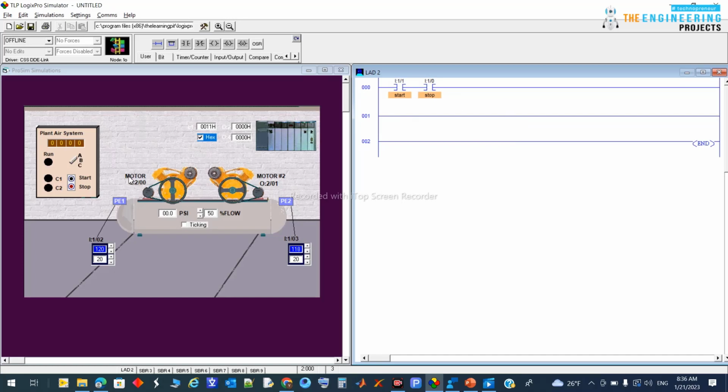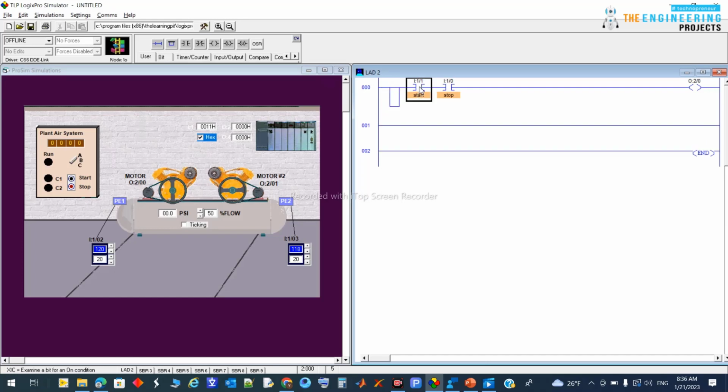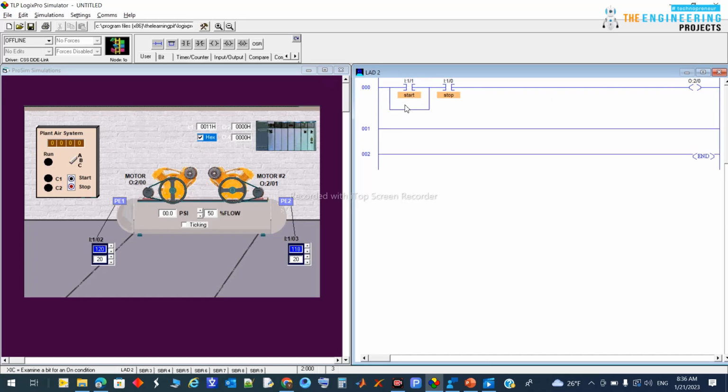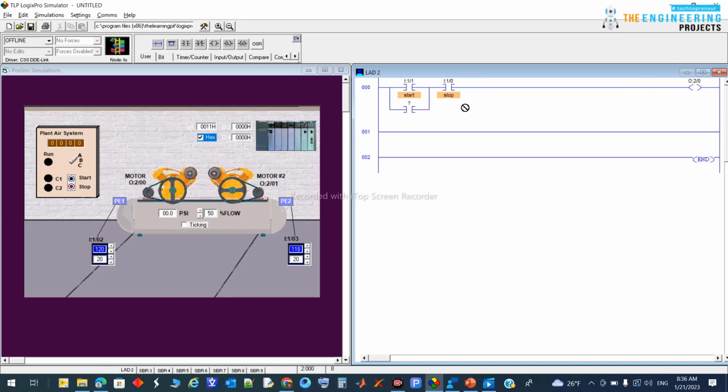And for sure we need to run this output. By having this output here, we also need to make a latch, so we need a parallel branch like this one. Getting this start, and also one contact for the latch, taken from the contactor of the compressor. So we get one contact here, making a latch for this one, and now we will stop here.